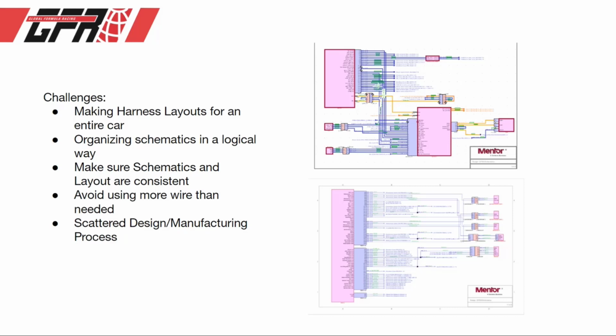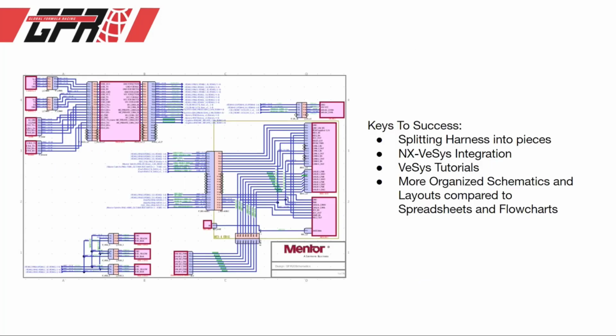With the integration of CAD software, DISW also solves the problem of excess wire lengths where they are not necessary, allowing us to optimize the harness for the car even more. Besides design, DISW also helps to resolve issues within the manufacturing of the wiring harnesses, in the sense that the tool can promote better organization by creating important documents such as bills of materials and manufacturing reports. Using DISW is a major key when it comes to building and manufacturing professional and efficient wiring harnesses.